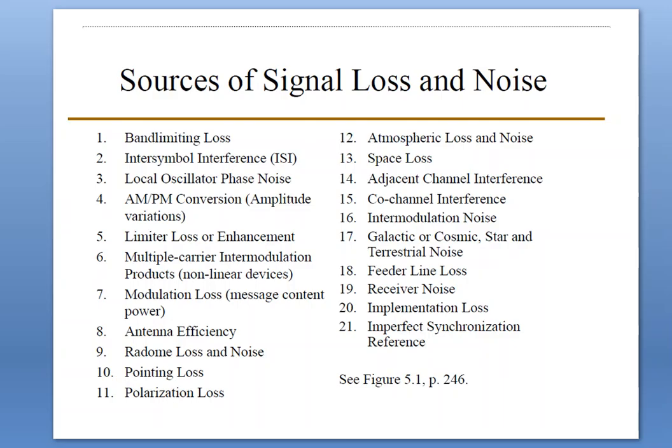When used as a reference signal in a receiver correlator, phase jitter can cause detection degradation, hence a signal loss. At the transmitter, phase jitter can cause out of band signal spreading, which in turn will be filtered out and causes loss in the signal. It is also one of the reasons for the forming of loss in a signal.